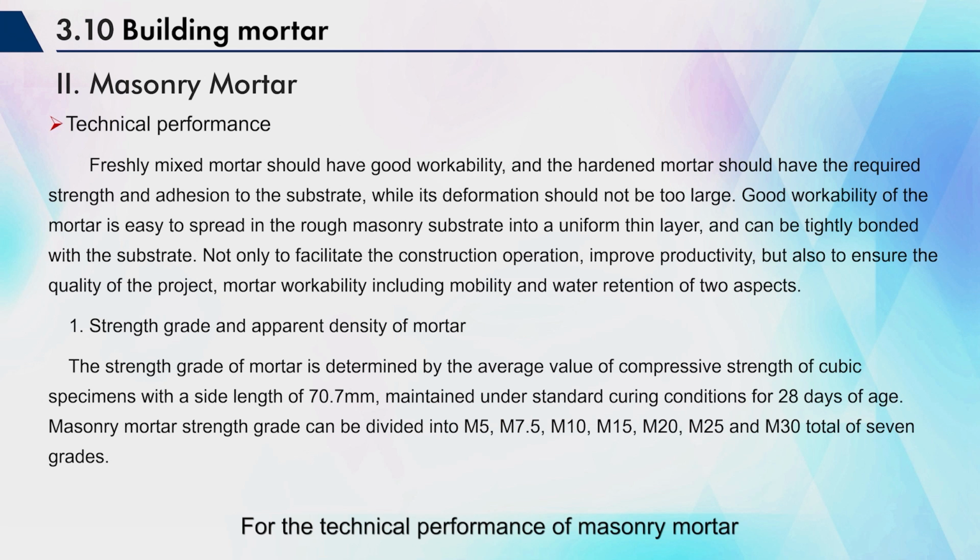For the technical performance of masonry mortar, fresh mortar should have good workability, and the hardened mortar should have the required strength and adhesion to the base surface without excessive deformation. Mortar with good workability is easy to spread into a uniform, thin layer on a rough masonry foundation, and can tightly bond with the bottom surface. It is convenient for construction operations and improves production efficiency.